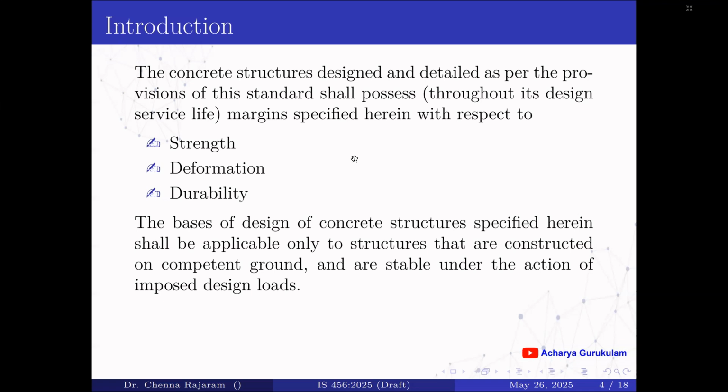Concrete structures designed and detailed as per the provisions of this standard shall possess margins specified with respect to the strength, that is corresponding to the stress strains at cross sections of members when the structure is subjected to design load combinations, deformations induced in members and in the structure when the structure is subjected to design load combinations, and durability. The basis of design of concrete structures specified shall be applicable only to structures that are constructed on competent ground and are stable under the action of imposed design loads.